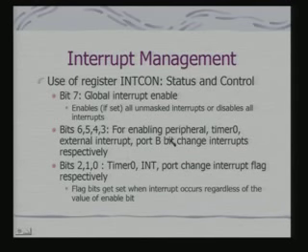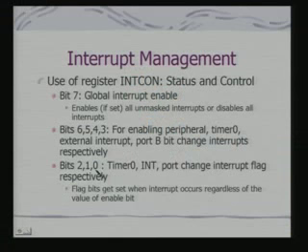Bits 6, 5, 4, 3 are for enabling, say, peripheral interrupts, timer 0 interrupts, external interrupt, and port B change interrupt respectively. In fact, when I enable peripheral interrupt, this corresponds to again another set of interrupts, because I can have many peripherals other than those which are listed here.